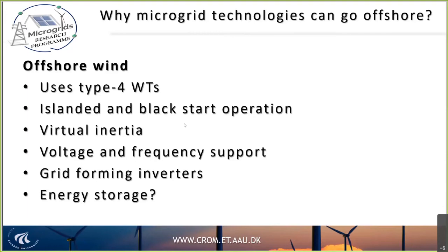One of them is to use islanded and black start operation. You have to think that sometimes the offshore wind farm needs some repair. For instance, the cable can be broken or cut at some moments, or you could have some blackouts outside. Because of that, you need to be able to operate in island conditions, because otherwise it will take very long to restart the whole wind power plant. And once you want to restart it, nowadays, unfortunately, diesel generators are required to energize the power plant. This is something that is against the philosophy of promoting renewables. And that's why we think that black start operation also needs to be there.